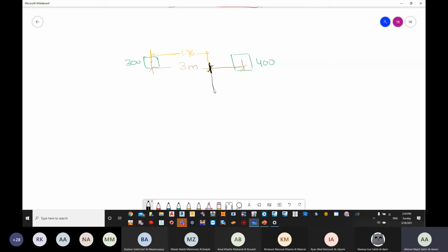This point is also going to be the center of my foundation. We said the length is going to be 4.6 for me, so this distance from this point to the edge of the foundation is 2.3 meters, which is 4.6 divided by 2, half of the foundation. The other half is the same thing, 2.3 meters.